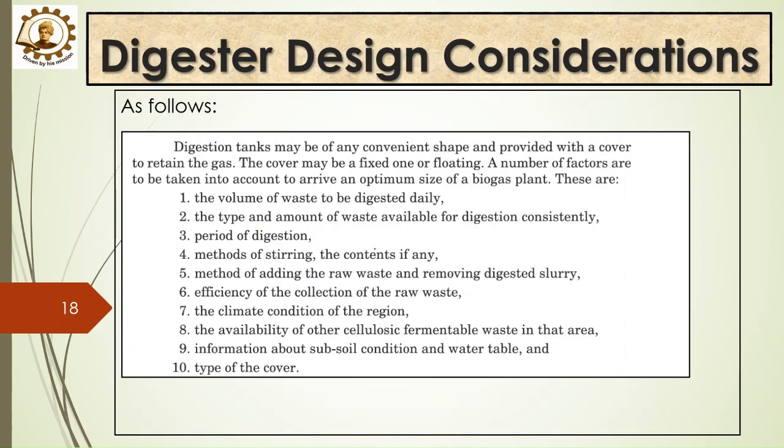Now, coming to another important part, digester design consideration. That is, how a digester should be designed. The first design consideration is the volume of waste that should be digested daily. Then, the type and the amount of waste. Then, the time that we need for digestion.